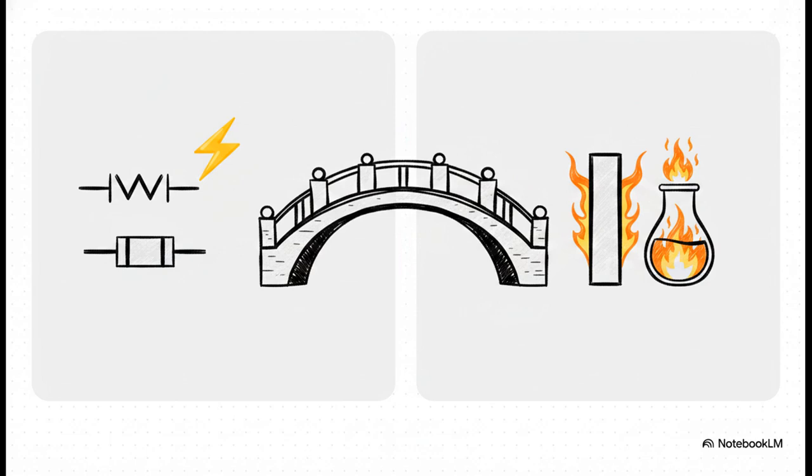If you know a little bit about basic electronics, this brilliantly illustrates how heat flux sensor behavior maps perfectly onto a simple RC electrical circuit. Instead of electrical resistance and electrical capacitance, we just swap those out for thermal resistance, Rsen, and a thermal capacity, Csen, attributed directly to the sensor's filling material. By mapping complex thermodynamics straight onto simple electrical principles, we can easily predict exactly how this sensor is going to behave over time.